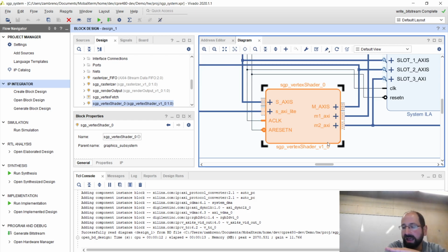Okay, there's an AXI clock and an AXI reset. What does the N mean after AXI reset? Any guess? It's inverted. It's negative edge. When it's 0, we're resetting. You'll get that wrong and you'll lose an hour, but then you'll remember that for the rest of your life, and that's okay. It resets when that signal is 0. You could put an inverter on there. It also shows a little inverter bubble here to indicate that's what is happening.